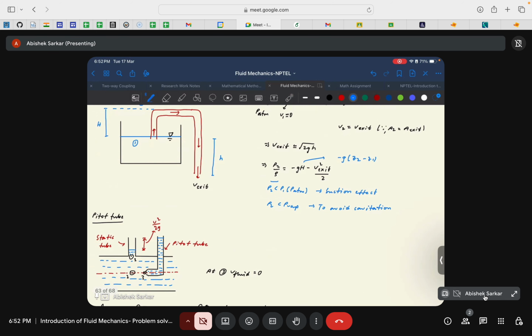But now you can see where the problem can arise in reality. Siphoning won't always work. There has to be a very ideal scenario for siphoning to work, and after some time the fuel may stop coming out. This primarily occurs because we are not considering the viscous effects and the frictional effects in the pipe.